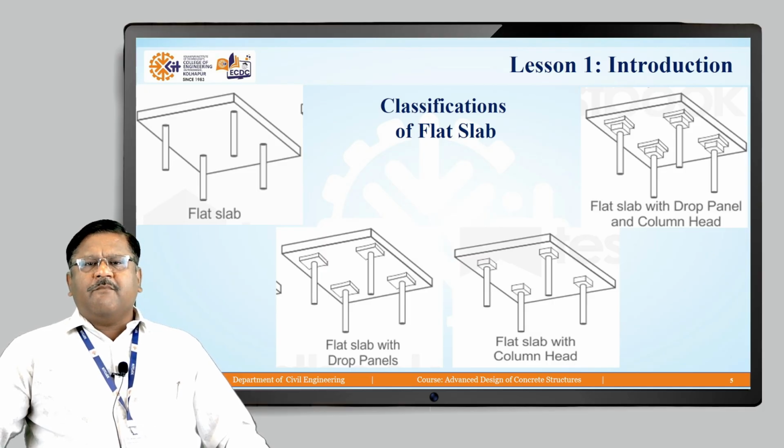Next is the flat slab with column heads. In such cases, the top portion of the column is flared, and the slabs rest on that flared column top. The last classification is the flat slab with drop panel and column head, meaning some projections are made below the slab and the top portion of the column is again flared, and such a combination is known as flat slab with drop panels and column heads.